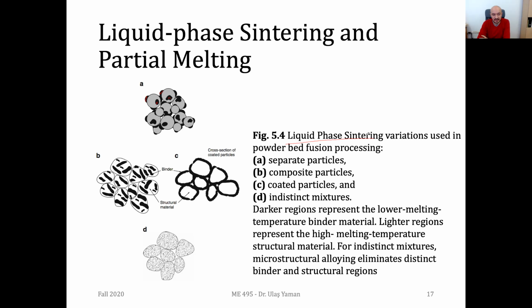You need to have proper secondary material, and you need to know the melting point temperature of these secondary materials, since at the end of the fabrication process, we don't want to have such binding material in our resulting product. So once the process is over, they should be somehow eliminated.